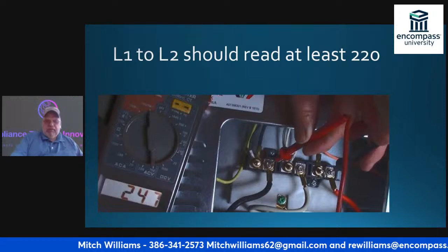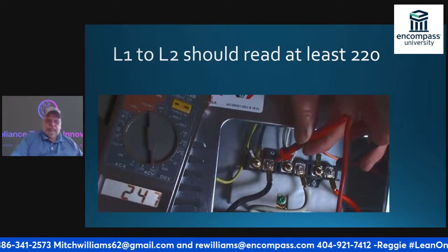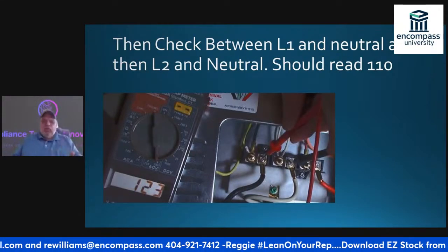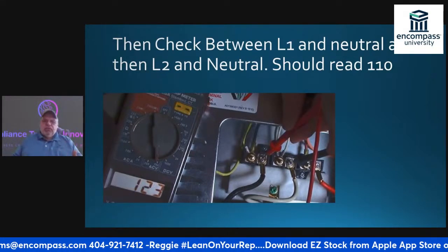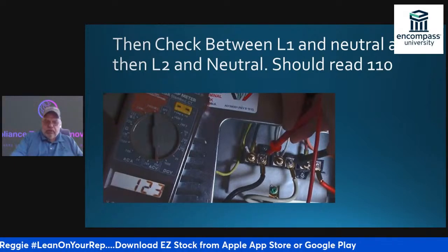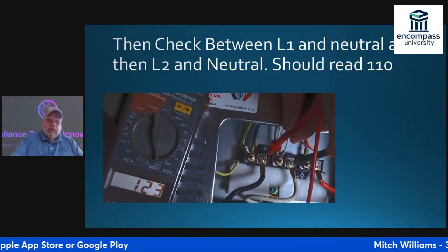This one happened to be 247 volts. Then I go between L1 and neutral and L2 and neutral, and I should get somewhere around 120 volts on this one.